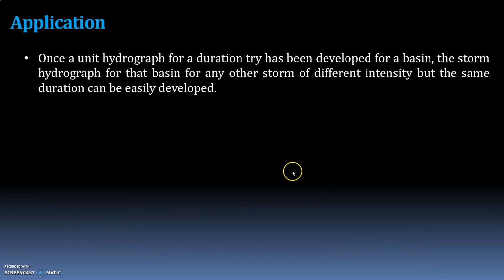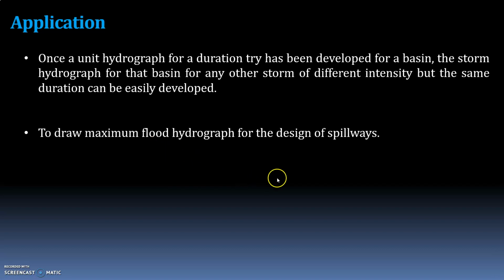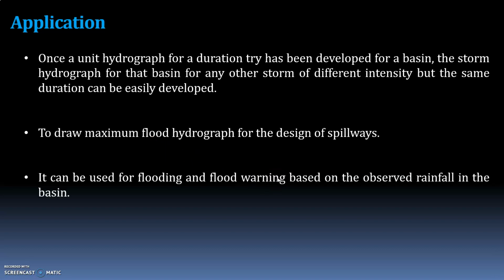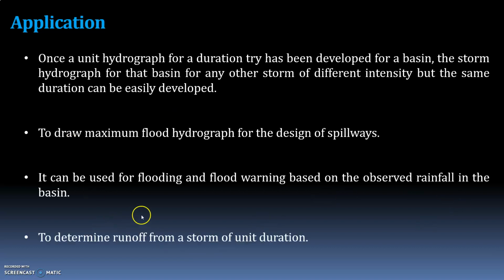The application of unit hydrograph. Once a unit hydrograph for a duration has been developed for a basin, the storm hydrograph for that basin for any other storm of different intensity but the same duration can be easily developed. It can be used to draw the maximum flood hydrograph for the design of spillways, and for flooding and flood warning based on the observed rainfall in the basin.